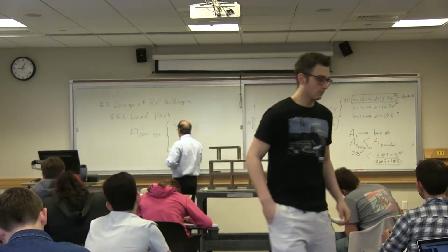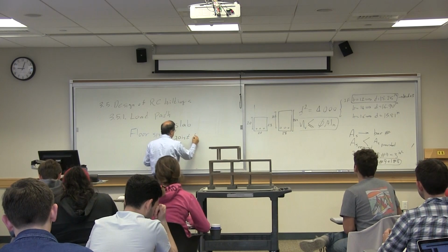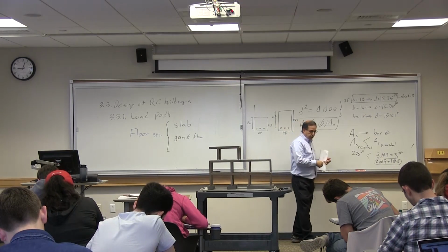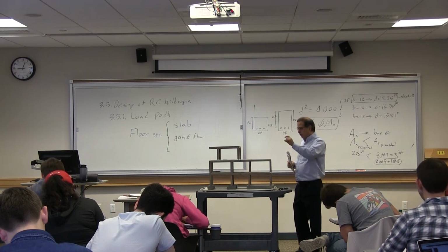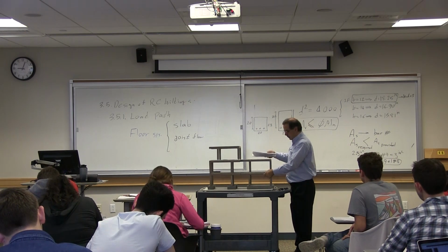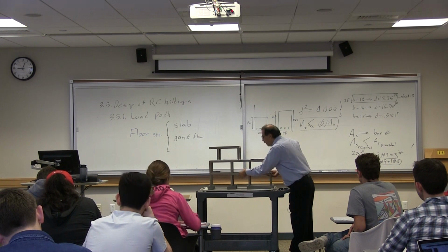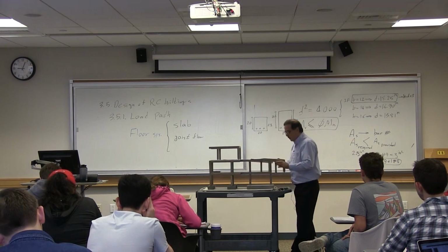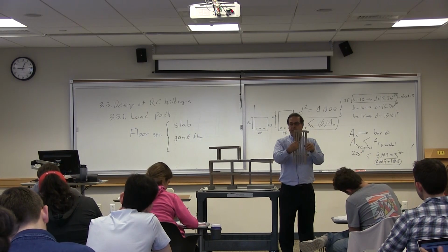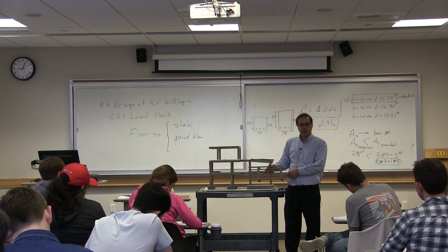We have another system called joist floor. Joist floors, unlike slabs that are constant thickness everywhere, are what we do is we run beams, smaller beams, usually in the longer direction.